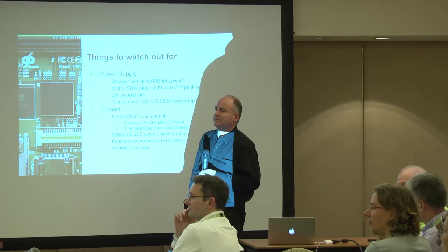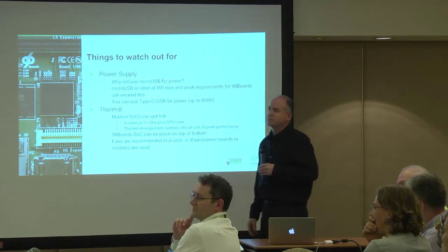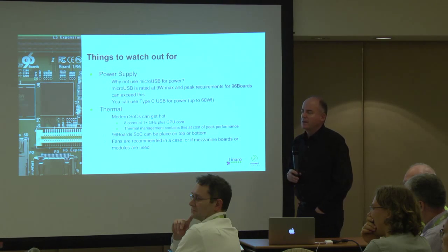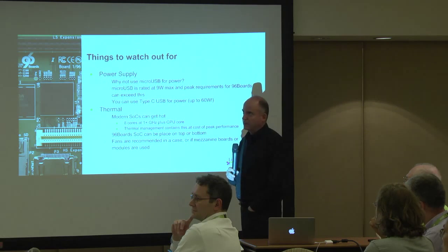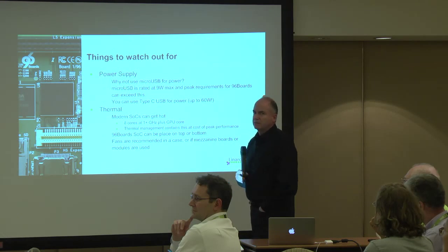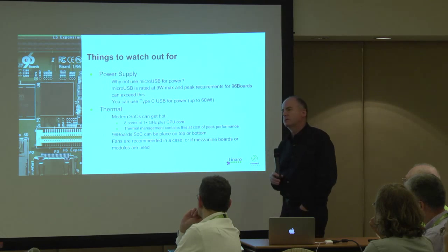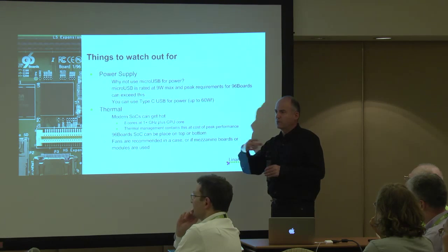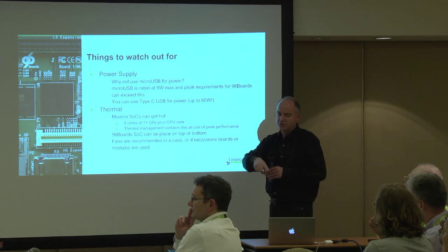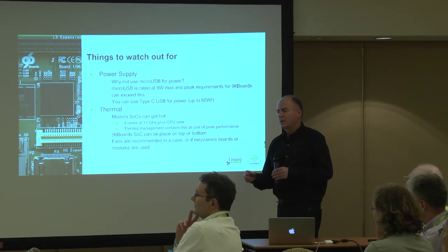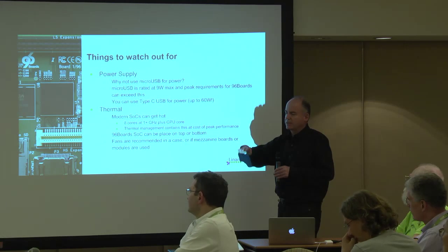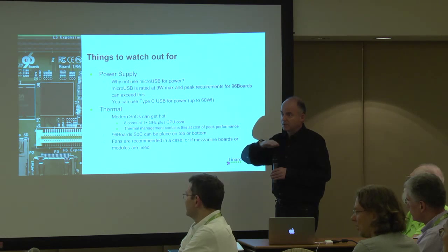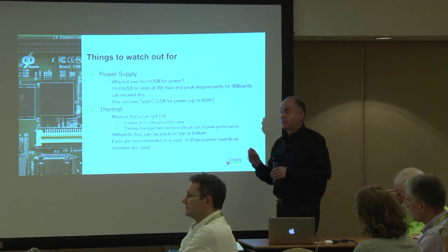Sticking with what you've given us so far, have you got height restrictions for heat sinks on both sides of the boards? Yes and no. There is a height restriction. The board has been designed to allow lateral airflow across the board between the two connectors. I'll show you a picture in a minute. There are height restrictions to keep the general level of the components low enough so that you can generate airflow across. The exceptions are heat sinks.